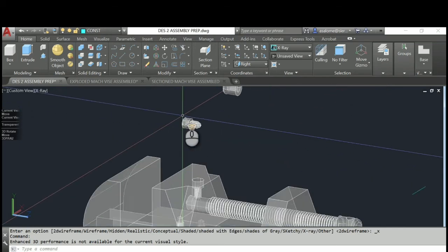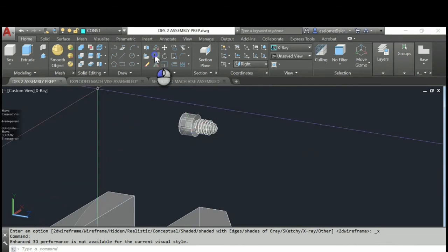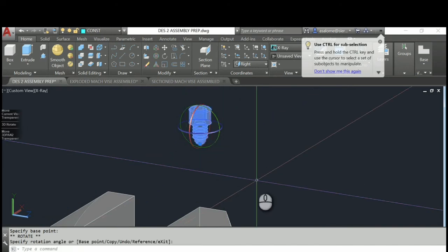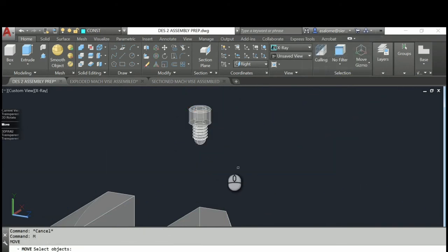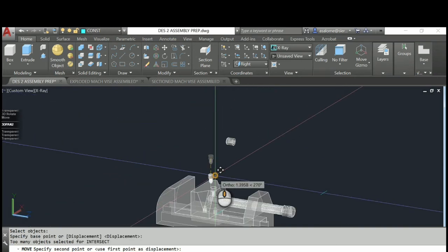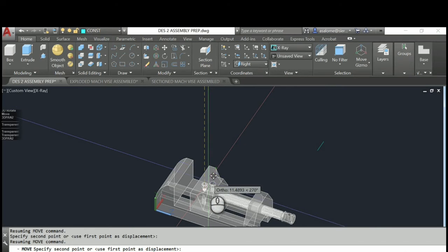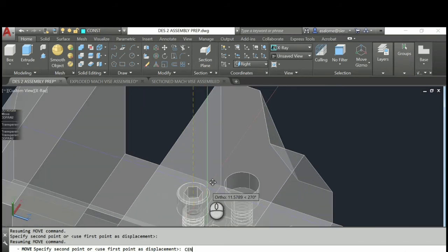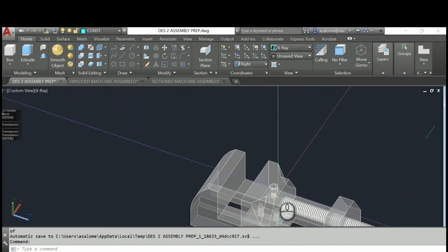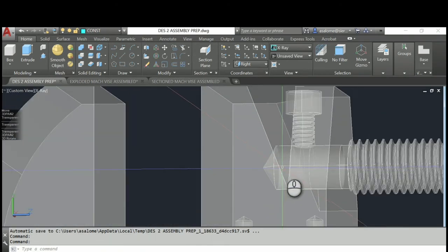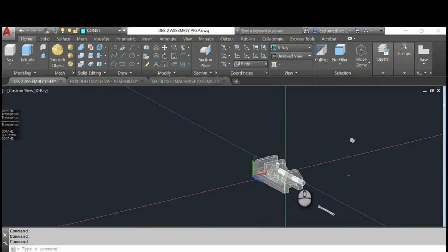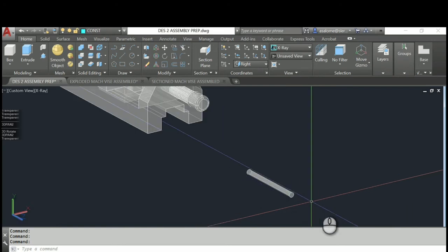So, FYI. Okay, we're going to rotate our adjusting screw. We'll pull it this way, and we're going to move it from the center at the base of the head to the center at the bottom of the counter bore. Double check your fit. Okay, and then the handle.